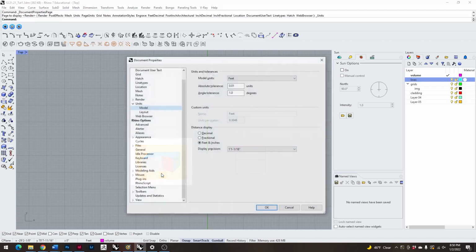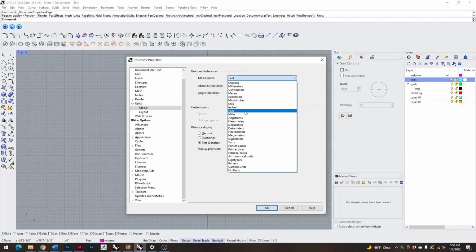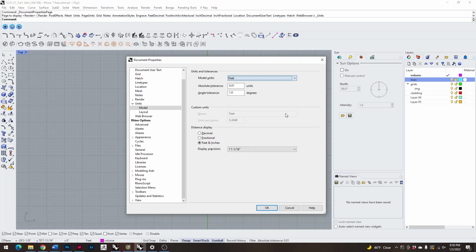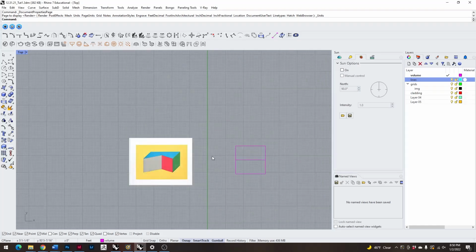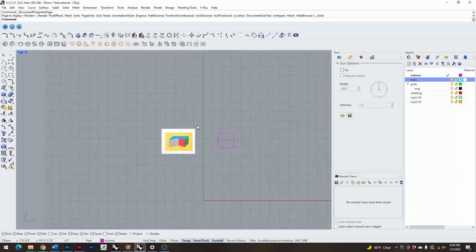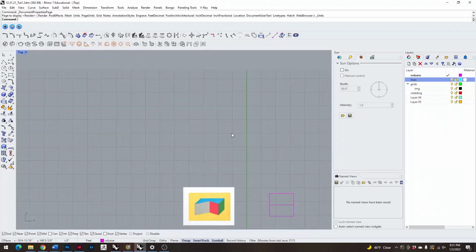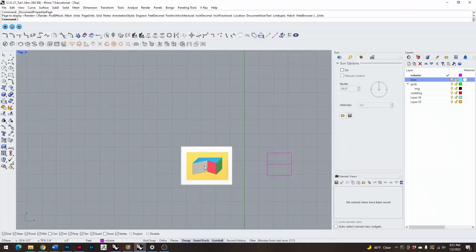The first step to setting units is typing in units and then opening up this directory, which will be a little different for Macs. You'll select feet because we'll be working predominantly in feet today. Then you'll press OK, and it might have to rescale some stuff, but in a blank Rhino document, it doesn't matter. So that will lead you to an empty Rhino document.